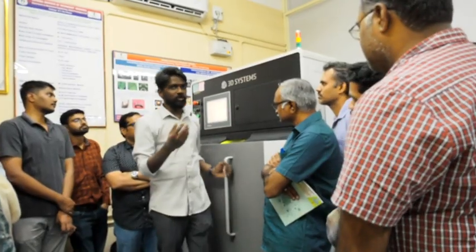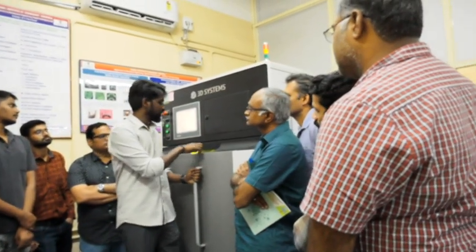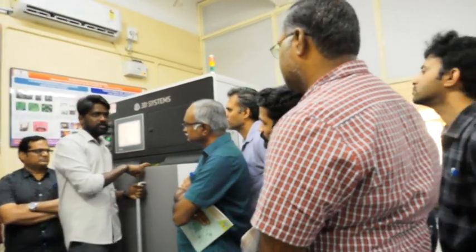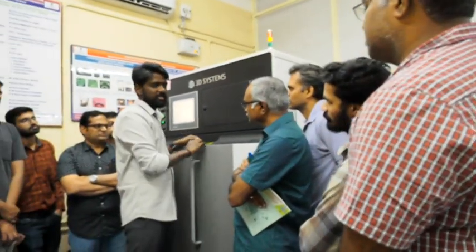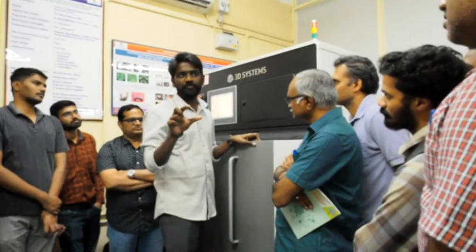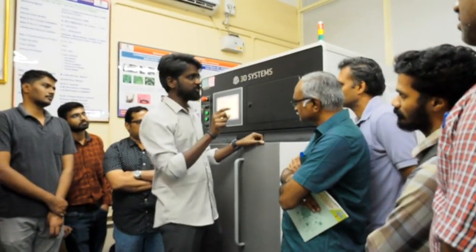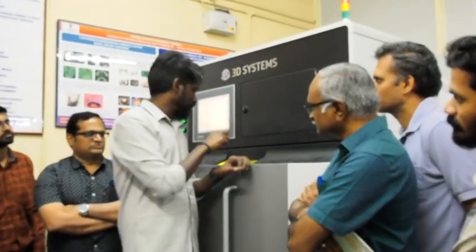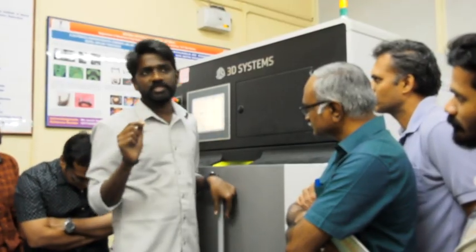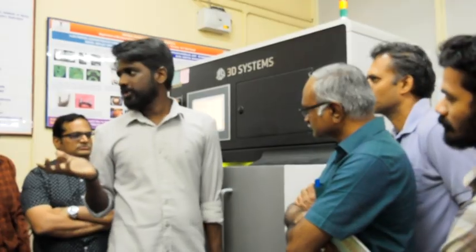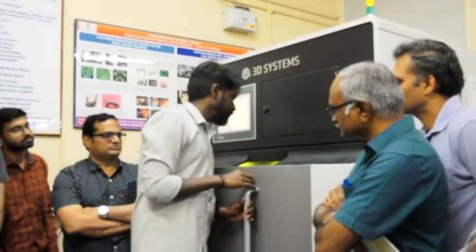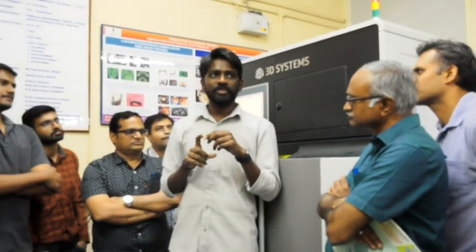And we have to load the powder inside the machine. There are two drop ports inside. With the help of the drop ports, we load the powder onto the supply piston. Actually, inside there are two pistons: the supply piston, followed by the sintering piston. In the supply piston, we have to load the powder. Right now we have already loaded SS 316, and 17-4 PH steel. Apart from that, first of all we have to load the part, which is the fabrication file.